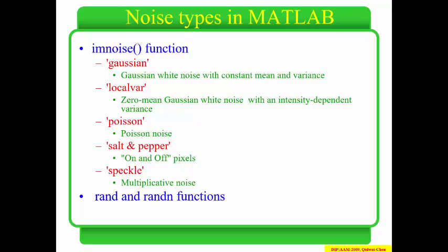No, it's not good. There is no noise that's good. I don't have any noise, any type of noise. Actually, all noises are noisy. Here, the white noise, when we look at its frequency spectrum, I will find that it has components at different frequency values, but all of the components in the frequency spectrum have the same amplitude. Right? Here we have another noise that has this kind of distribution that is related to Poisson.